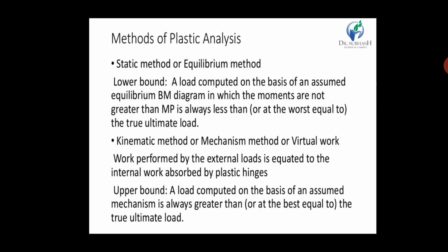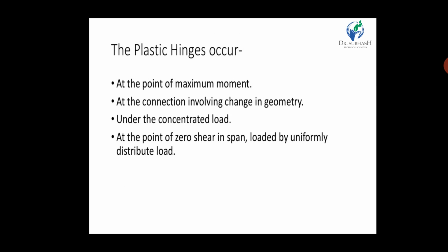The work performed by the external loads is equal to the internal work absorbed by the plastic hinges. The upper bound: a load computed on the basis of an assumed mechanism is always greater than or at least equal to the true ultimate load. So these are the two methods when introducing plastic analysis. The first is the static method and the second is the kinematic method, the upper bound theorem, and the static theorem with the lower bound theorem. So these are the two types of method we use.